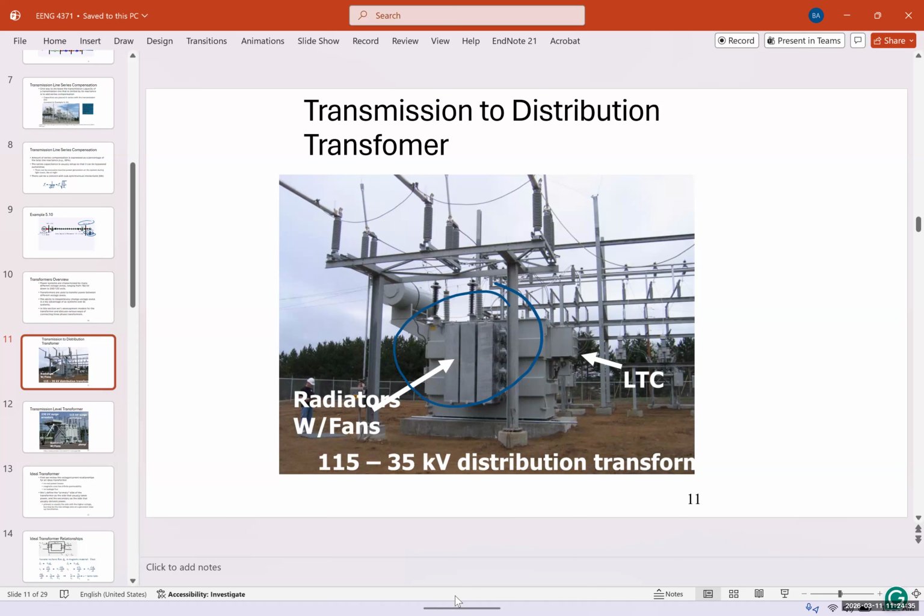And sometimes you have a circulating oil system. Some of them, like the very high voltage ones, have a pump. And they have filters, so if you have debris in there, it's going to block it, it's going to get hot, and it's going to damage the whole system. So you need to have regular maintenance on a transformer. It's not like a car. Every 5, 10, sometimes 20 years, you have to do regular maintenance.